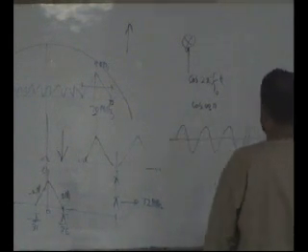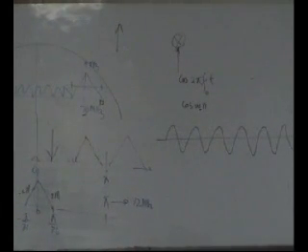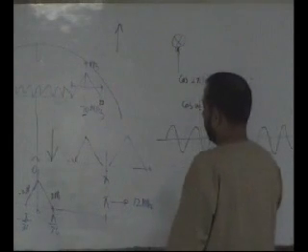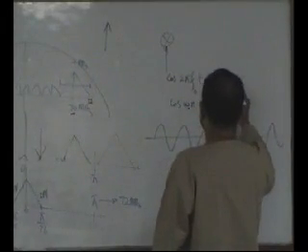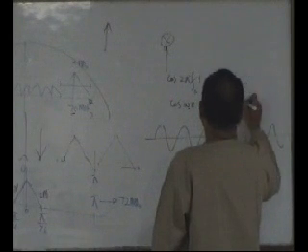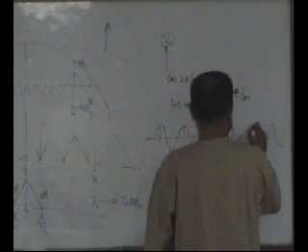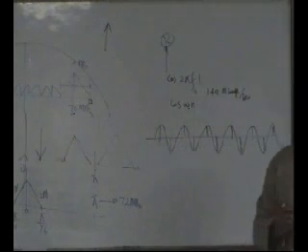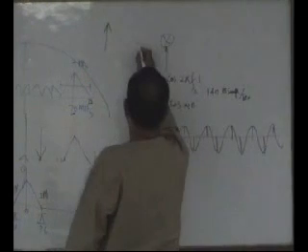At what sampling rate can you create a 70 megahertz cosine? How many? 140. At least you need to have 140 mega samples per second to generate such a cosine. Okay. If you are doing it digitally, in every second you must have 140 mega samples. Okay. This is your digital signal, which is your video.